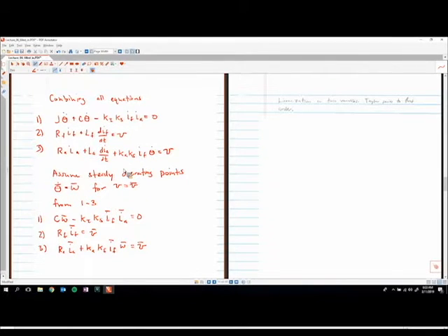So let's talk about what accurate means here. Accurate is a really tough thing to define for the transition from a nonlinear system to linear, and that is highly dependent on the nature of the nonlinear expression. That's an entire 7,000 level course in itself in electrical engineering. So just keep in mind that the system becomes less accurate as we deviate farther away from the operating point, in general.